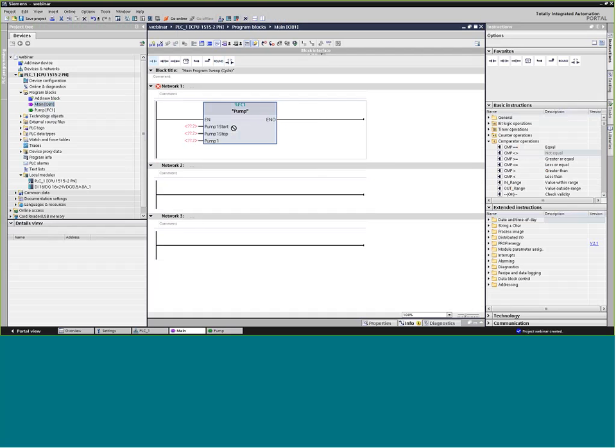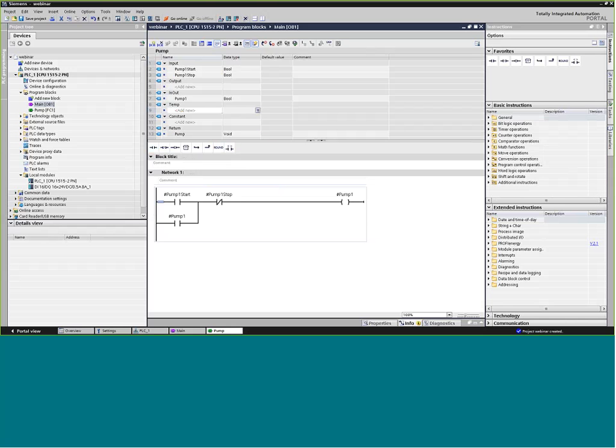So in other words, you get the concept there that we're actually going to be using a subroutine that we can pass parameters to and call it over and over again without having to see all the logic in our OB1. And OB1 can end up looking much more like a table of contents, where if I right-click on FC1, I can say open it, and it shows me the logic.